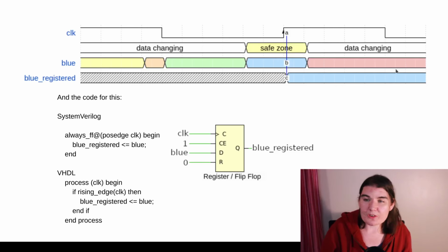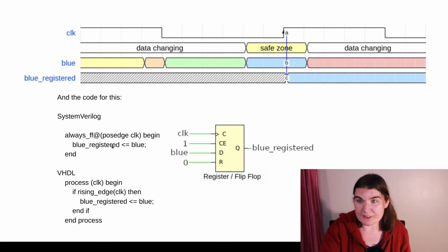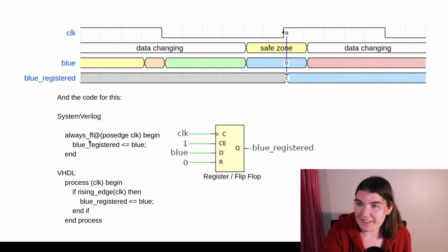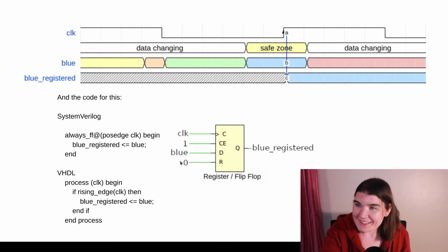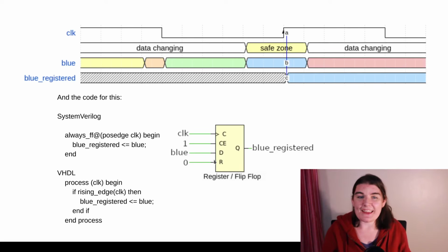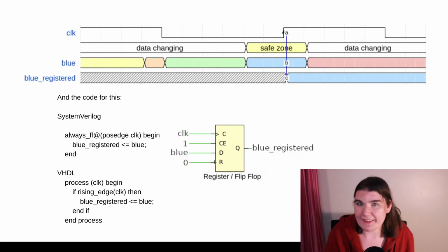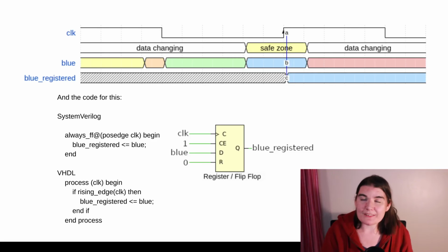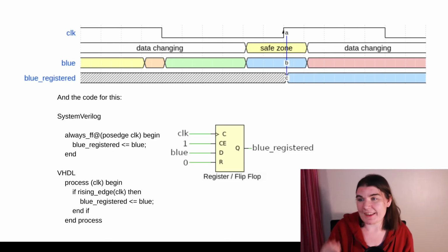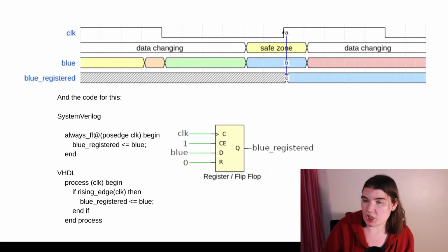So if I want to make a local copy of a signal, I can type this. And what this will do is this tool will take a look at the code I wrote. It will recognize this format. FF is flip-flop, which is another name for register. This will turn it into this. And so this is a basic building block inside the FPGA. The FPGA is made up of fundamental electrical logic units like registers, but it also has LUTs, which are lookup tables, which aren't clocked memory.